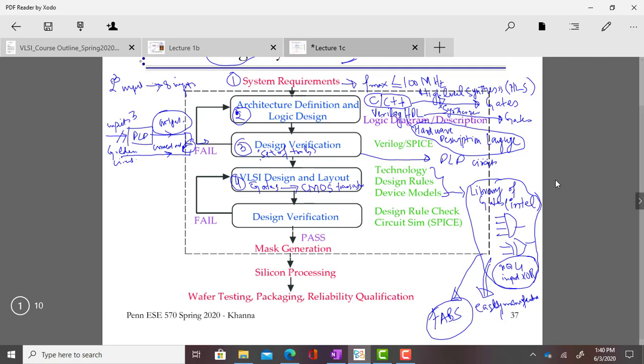And so in the fourth step, one thing we do is we map from gates to CMOS transistors, or we can say to library gates. But these library gates are not in this form, they are in transistor form. So they are like a huge chunk of transistors connected in some fashion. This step is called technology mapping, or tech mapping.